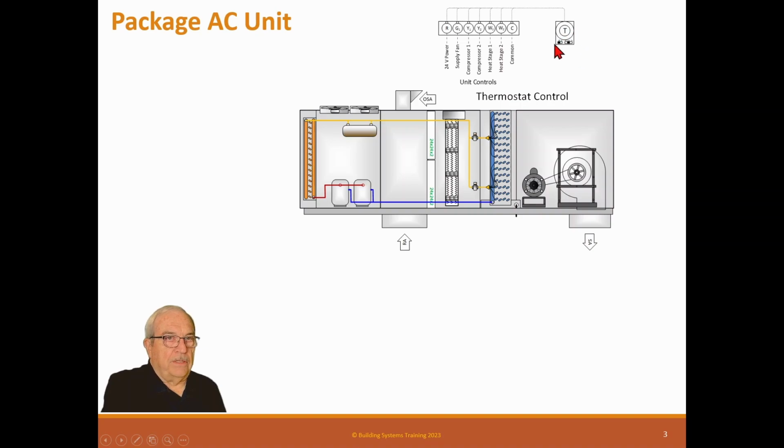However, these older type thermostats are not preferred, because when you switch the unit on and switch it to cooling, it's in cooling and it's on. The compressor will cycle on and off to maintain the temperature set point, but the unit's on, so it doesn't go off at night. It runs all night long. And this is very, very energy inefficient.